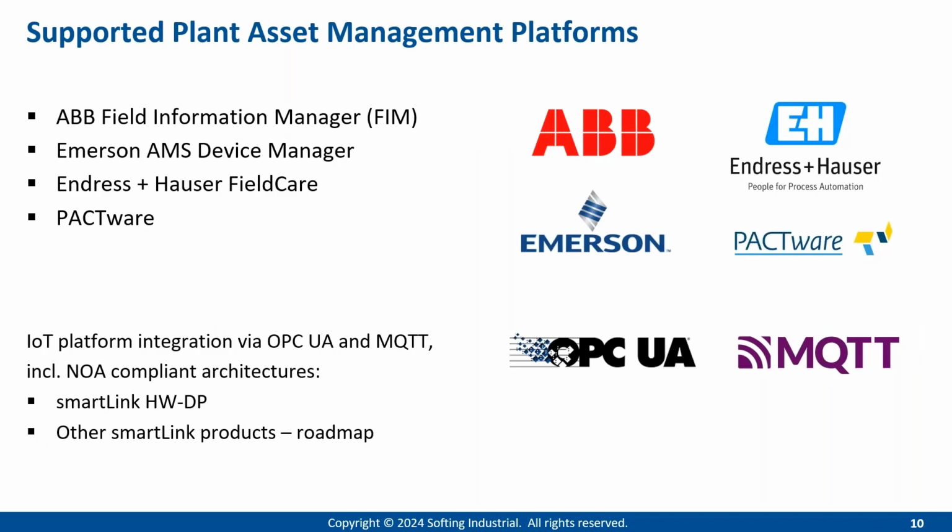Currently, we support already a number of asset management applications. As I mentioned before, the EDD FDI-based ones from ABB, that's the Field Information Manager, FIM, and Emerson AMS Device Manager. We also support FDT frameworks. Currently, we always test here with Endress+Hauser FieldCare and PACTware. But as mentioned before, other frameworks using FDT, like Yokogawa PRM or Honeywell FDM, are also possible to be used here.